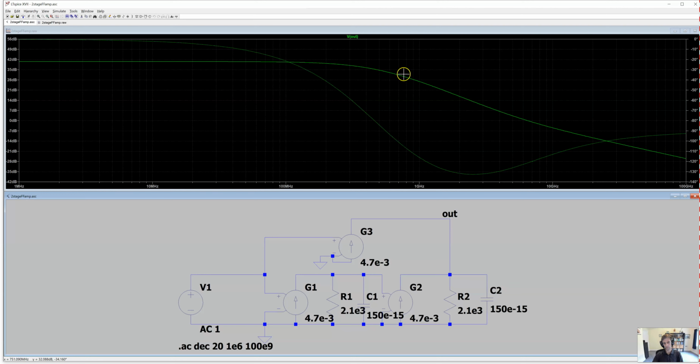It's a little bit subtle, but if you take close note, you'll see that the magnitude response is rolling off here at 40 dB per decade, and then it does bend slightly upward due to the lead compensating resistor. The effect of that is perhaps more obvious looking at the phase response shown here as the dotted line, where you see clearly the phase response is going down towards minus 180 degrees, but then curves back up and approaches minus 90 degrees asymptotically. Again, that's because at high frequencies, the response is solely determined by the path through GM3 here.